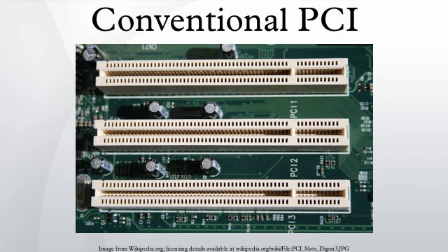Starting from revision 2.1, the PCI specification includes optional 64-bit support. This is provided via an extended connector which provides the 64-bit bus extensions AD63:32, CBE7:4, and PAR64, and a number of additional power and ground pins. The 64-bit PCI connector can be distinguished from a 32-bit connector by the additional 64-bit segment.